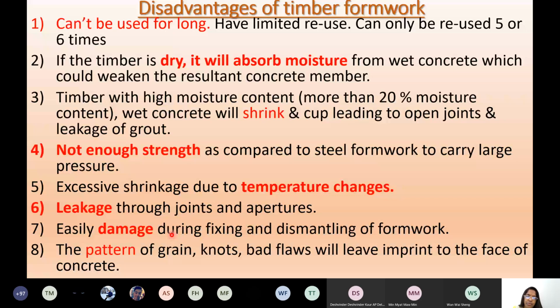Wood is not so strong. At times, if you pile it too many, chances of breaking. If you want to speed up the construction, you pile it to a very high height, bring it to the side, chances of breaking, right? Then the pattern of grain, knots, bad flaws will leave an imprint on the face of the concrete.